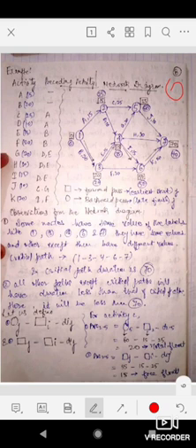If you want to calculate free float, how can we calculate it? We can calculate it by earliest start time of forward node minus earliest start time of backward node minus project duration. So total float and free float can be calculated by using these two formulas. So we have considered one example of critical path method. In this example we have found the critical path and its duration, that is the duration of the project, and we have calculated total float and free float, and we have also made a precedence diagram by using this table.